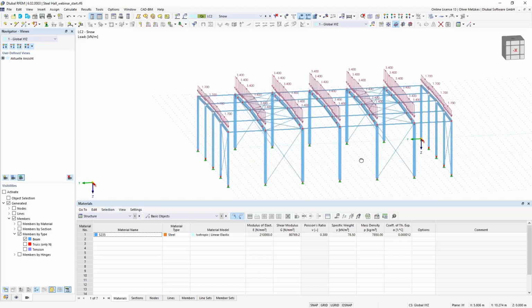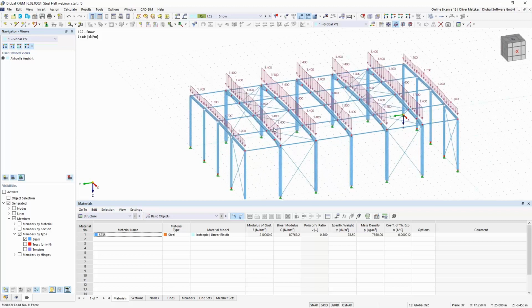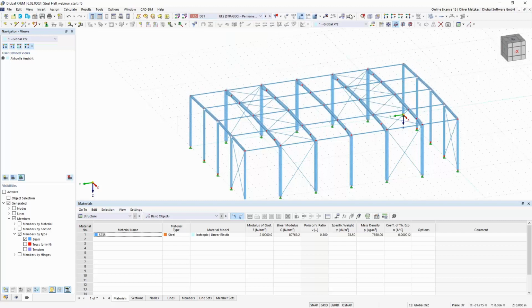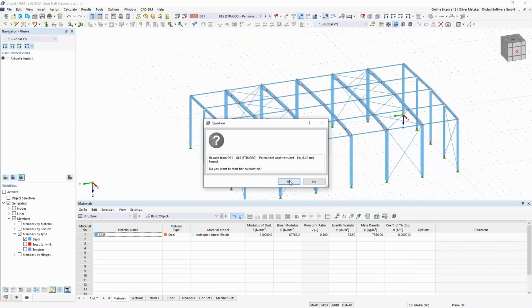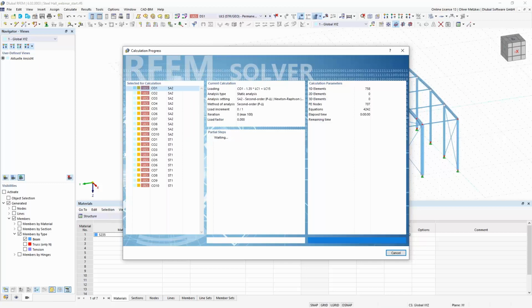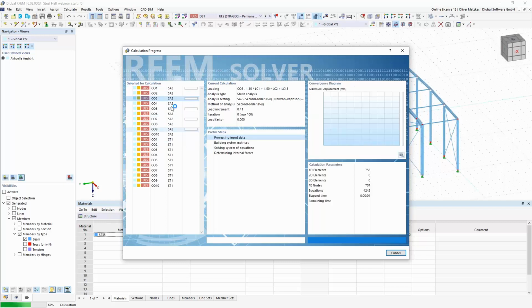Okay, so now I have changed those two settings, and I want to run the stability analysis now. I think we still have it activated from the example before. So if I calculate my design situation number 1, I have my 10 load combinations, static analysis, and then stability analysis. And now I would expect to also get these lateral torsional buckling shapes.